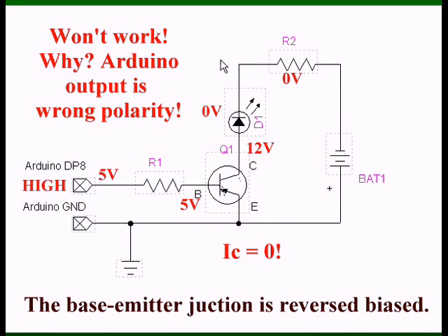Now let's connect a PNP up as if it was in the sink configuration like we would an NPN transistor. Of course, I'm going to have to reverse my battery. The positive's going to go to ground. The negative has got to go, and I also have to turn my LED around. Note, if I didn't mention it before, the arrow points to the negative material in the LED. That's not current flow. You should have seen this if you'd already seen my video on NPNs. But nonetheless, this will never work no matter which way I turn the battery.